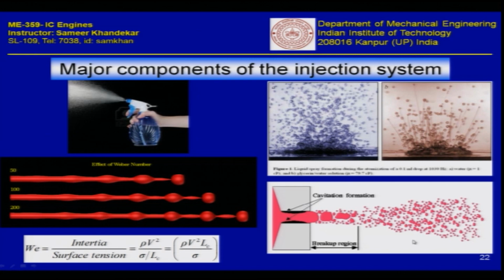Because as you will recall, we need to break down these particles into very small, let us say, diameters, so that the air which we have supplied comes in good contact with this diesel spray, and then once the combustion starts, we finally lead up to complete combustion, as the combustion efficiency has to increase.